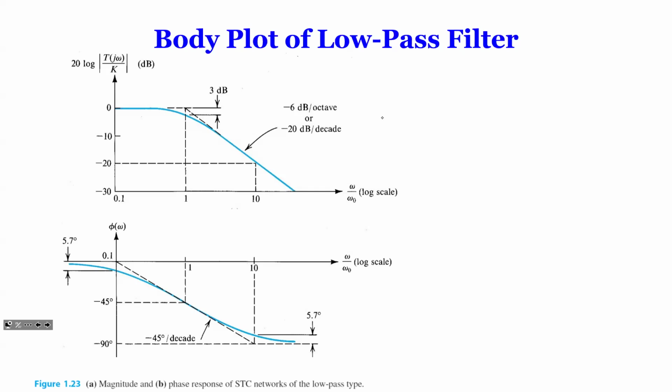In this case, this range is called low frequency or middle band, but it's like a low pass. For high frequency, the output is smaller and smaller. So it's like a low pass cutoff. And this is the angle, the phase shift, maybe 0 phase shift, then 45 degrees, and all the way to a 90-degree phase shift. So that's a Bode plot.